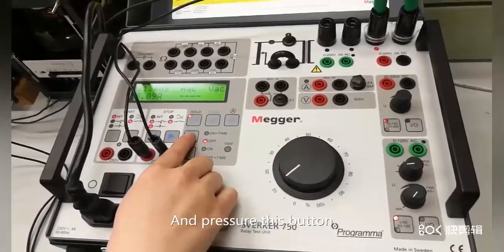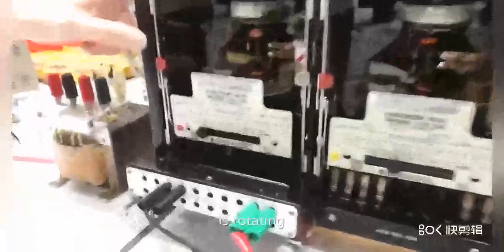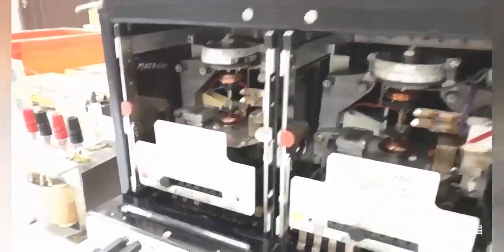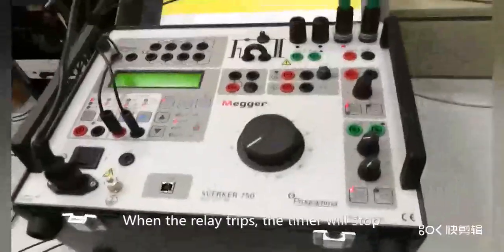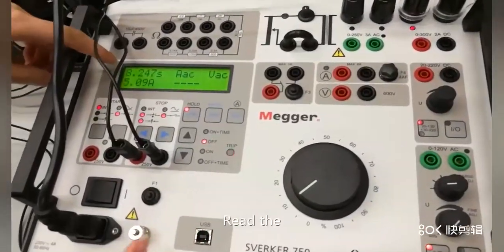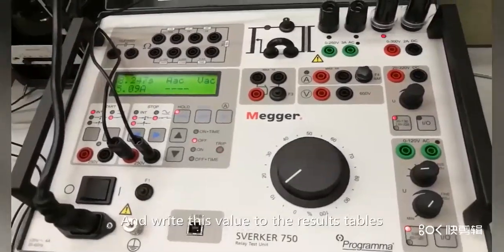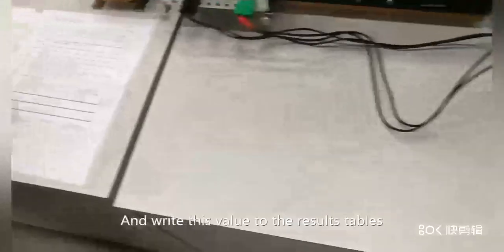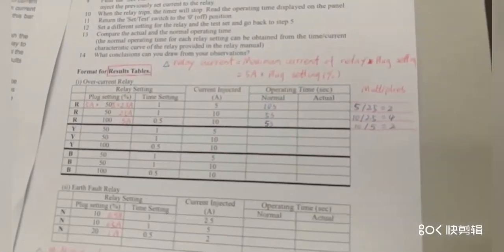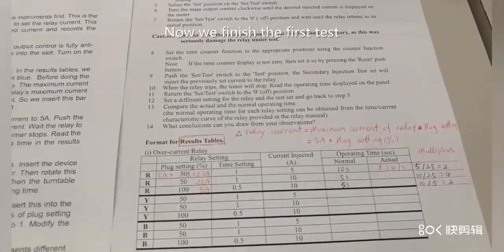Press this button, and you can see the timer is rotating. And when the relay trips, read the time, and note this data to the results tables. This is the actual operating time. Now we finish the first test.